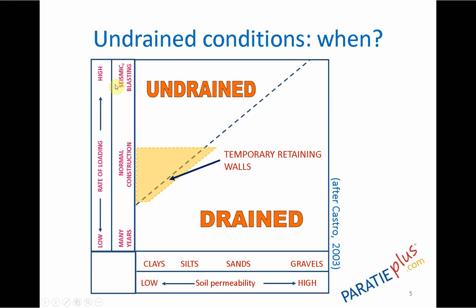When there is a very fast application of loading, even sands and even gravels may sometimes undergo undrained condition. This is the case, for example, of liquefaction, that is a typical effect for loose sands in seismic condition.